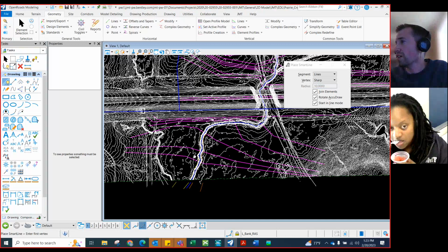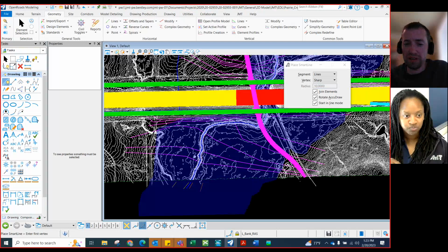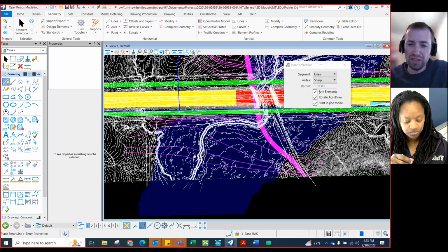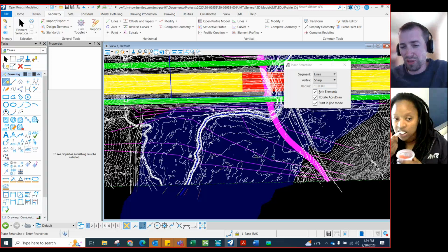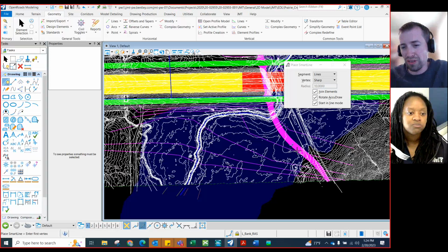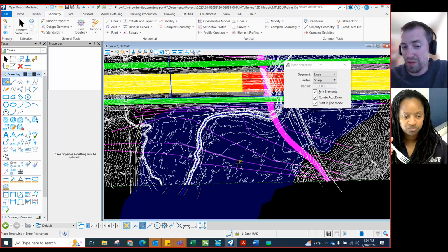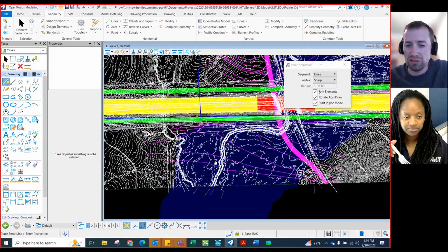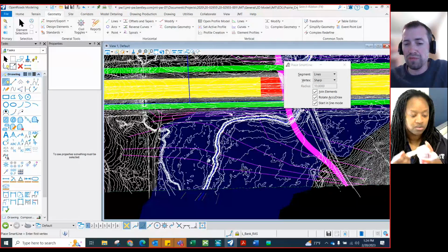So a lot of times what's helpful is you will have the floodplain. And so you could take your 100-year and go 1/3 of the way across the floodplain, or 1/3 of the way across how long you drew the cross sections, guessing what the floodplain would be. So keep that in mind when you're doing cross sections. When it says 1/3, it's assuming that's what you're guessing the floodplain will be.